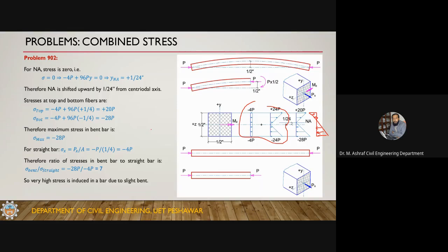Another possibility is that you check the design with this eccentricity, and if it is within a certain permissible limit, that the stresses are not exceeding the strength of the material, or the demand is still within the limit of the capacity, then you say it is okay. You just fine the contractor with a certain amount, because this is a mistake and he should do work as per the standard and specifications. You say it is acceptable to me, do nothing, and just fine him so that next time he is very careful.